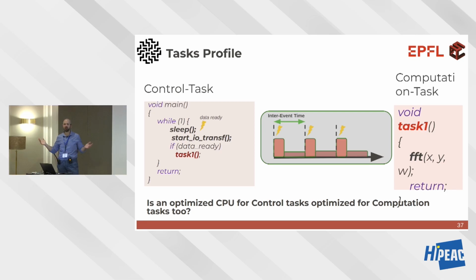Then you get an interrupt, an event that could come from a timer if you are timely getting data from outside, or maybe you get a GPIO triggering from another device and so on. You wake up, you jump to the starting of your transfers of data coming from sensors. Maybe you have an ADC, so you're taking them on chip and so on.